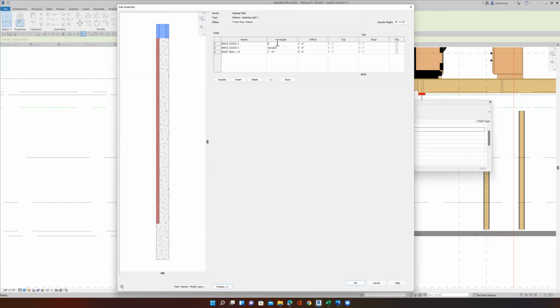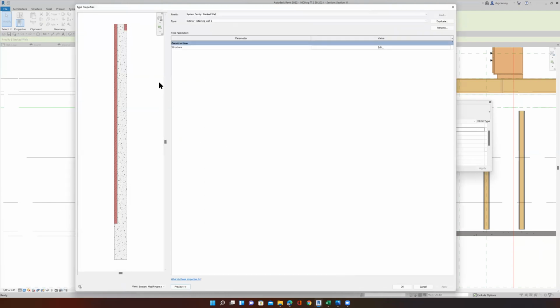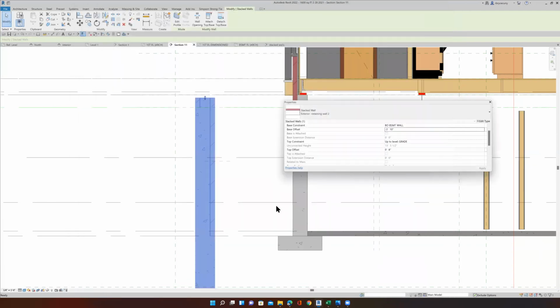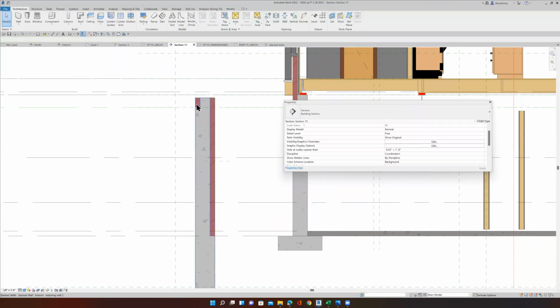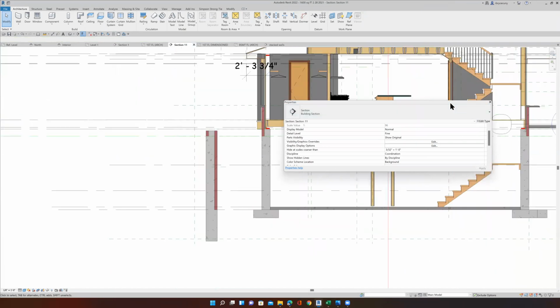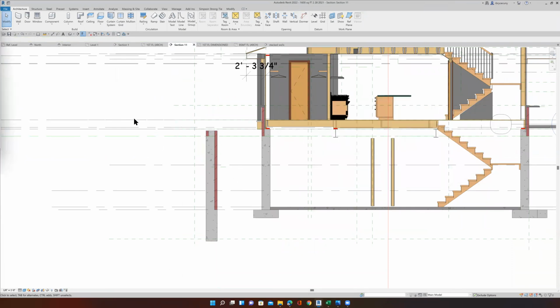Let's see what happens when I make this 8 inches. The variable will pick up the difference. Let's see what happens now. Oh, I like it. Look at that. So now my brick is on the outside just to there. I'll put a cap on top of that. All right, so now I have my brick ledge in, and this is a retaining wall. On this side, the earth will be, and on this side, we're forcing an areaway, a walkout. So back to the basement plan.